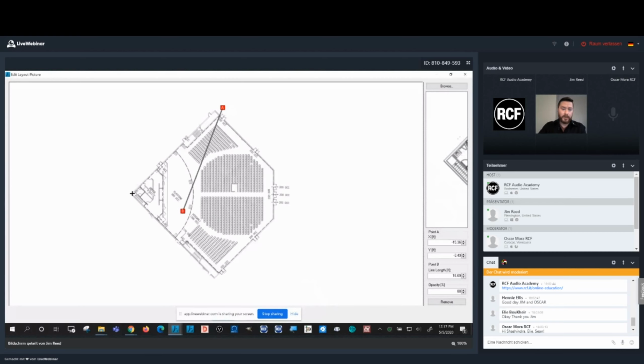I know that from one corner of the room to the other corner of the room is roughly 128 feet. So what I'm going to do is drag these 2 points from one corner of the room to the other. I'm going to make sure that I am being as accurate as possible when doing this, because this is going to determine the scaling for the rest of the room. And when the rooms get larger, even the slightest mistake can turn into a big mistake as the scaling of the room increases.